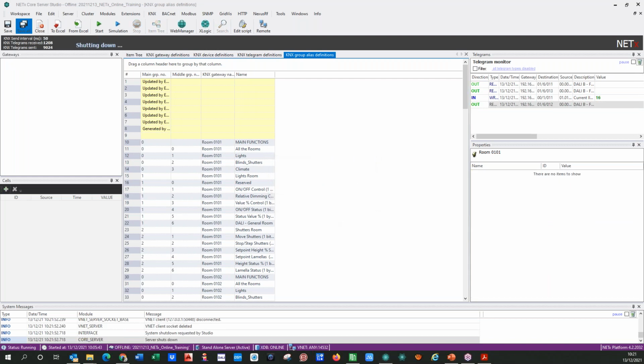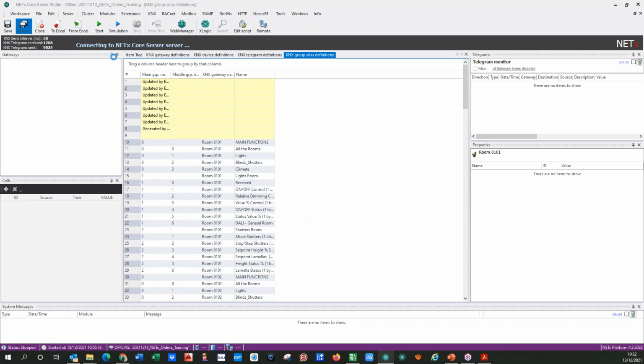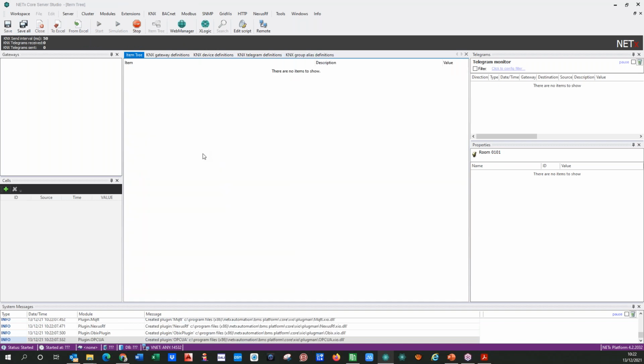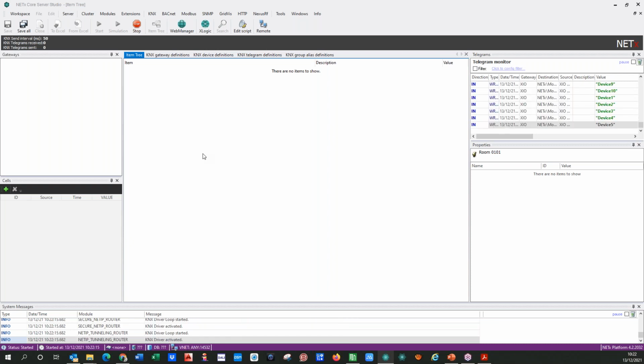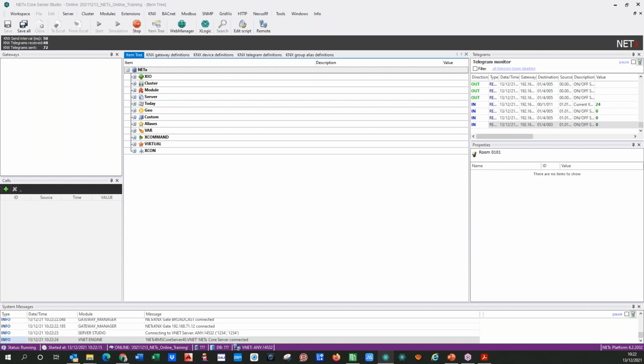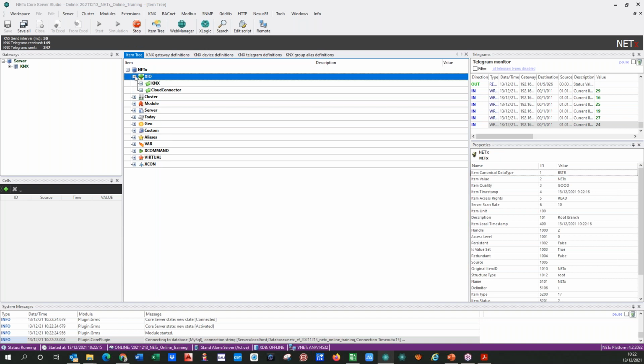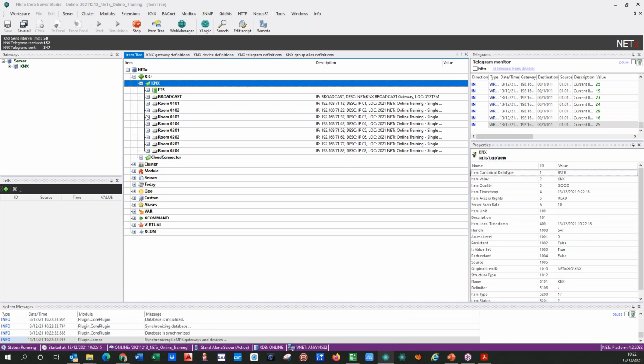And you will see at the end, as I'm finishing the first session now, how it is done. The change of the DPTs in the Telegram definitions is sometimes necessary because sometimes there are private group addresses or private DPTs from a manufacturer that is in the BMS but is not in the ETS. And other times it's because you haven't done it in the ETS. So you can finish the work here, or you can do it before in the ETS, of course.